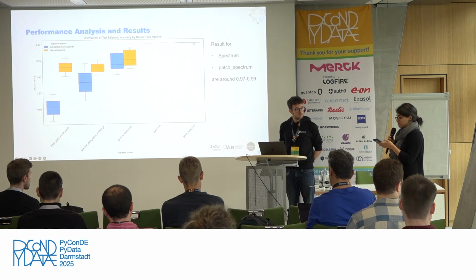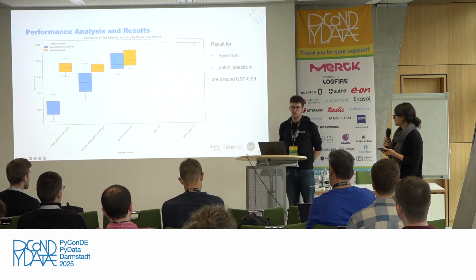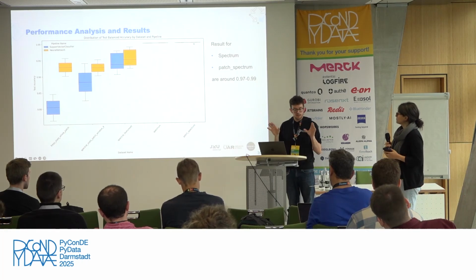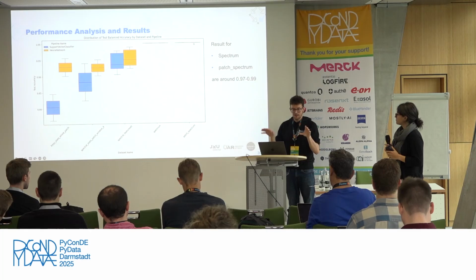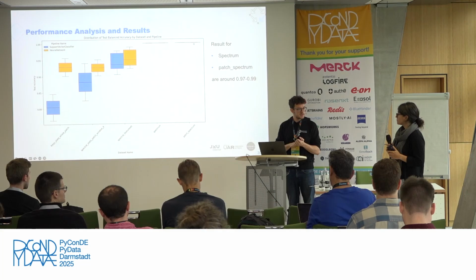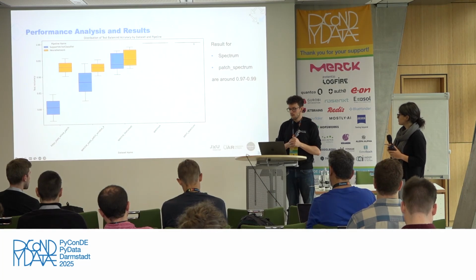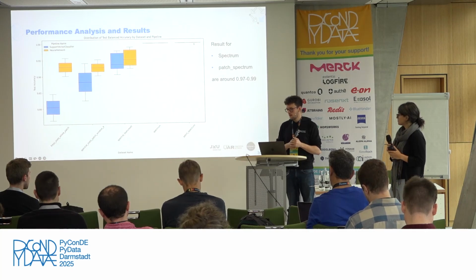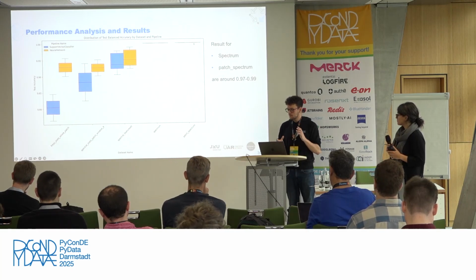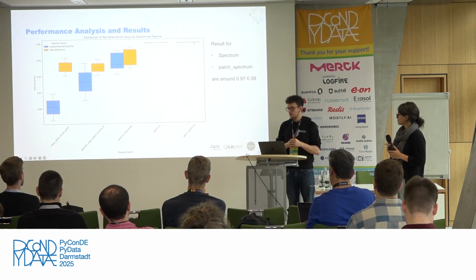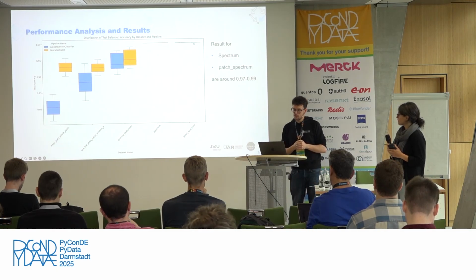I think one more. The model seems to be really good to detect bad nozzles, but what about okay nozzles? Did you set a threshold? That's another issue with the data package right now. We set it up so we can try to differentiate between good and intact, but it will be interesting when a production machine is first used with this system to see how the degradation happens over time and how well our system reacts to it. But I listened yesterday to a talk about changing your models a bit to maybe try to detect okay nozzles well, or at least avoid those if possible. Yes. But this is an issue in production we have to tackle in the future.